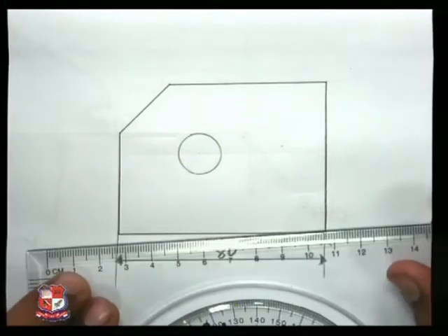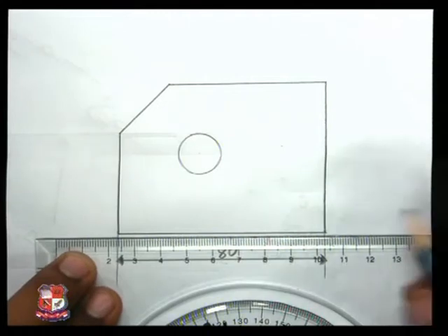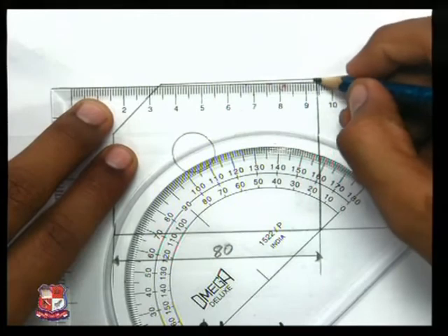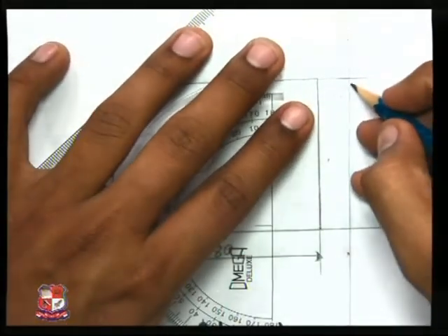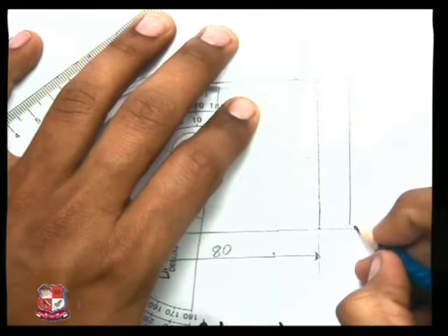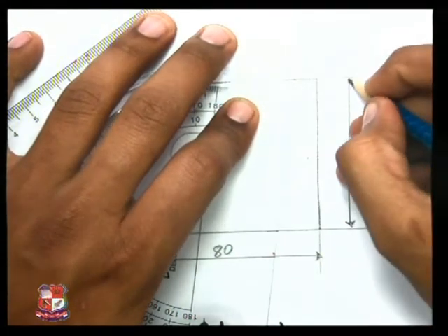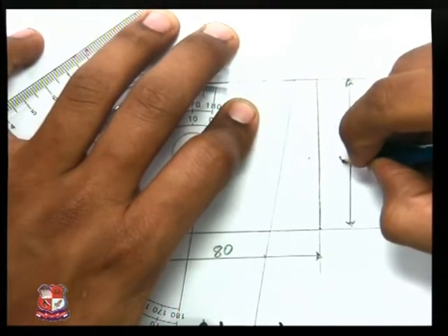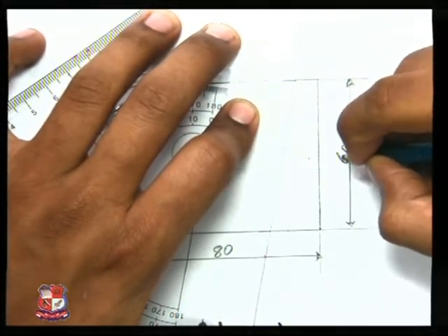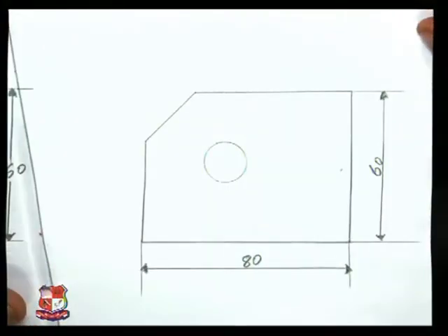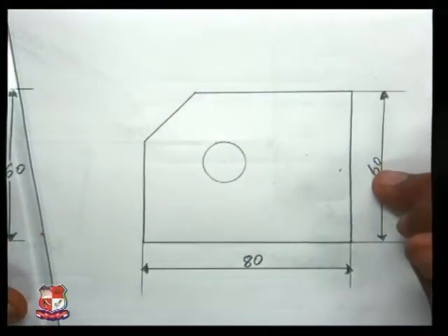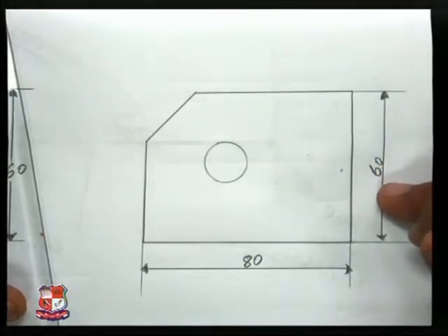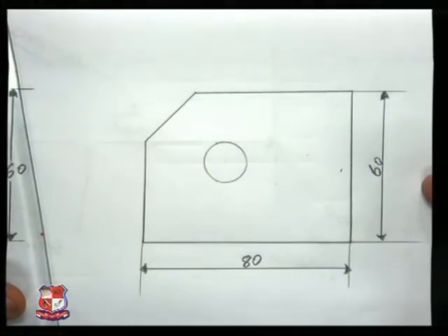This is horizontal dimension. Now let's have a look at the vertical dimension. Continuous dimension line, dimension above dimension line, but the written dimension should be parallel to the line.